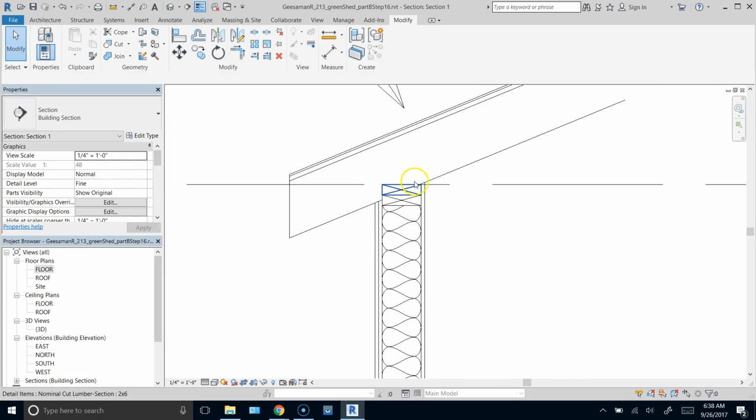And what they will do in the field is they will cut out a portion of the roof rafter that is called a bird's mouth, and they will notch it so that it actually sits on top of the top plate. We can't put a sloped rafter on top of a flat plate and expect any true contact. They do make special seats, which are pieces of bent thin gauge metal, that will allow you to do that, but it's much easier and cheaper to just notch out the rafter and sit it on top. So now we have our roof rafter bearing correctly.